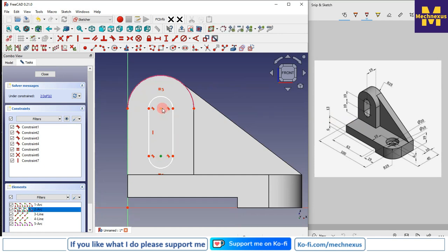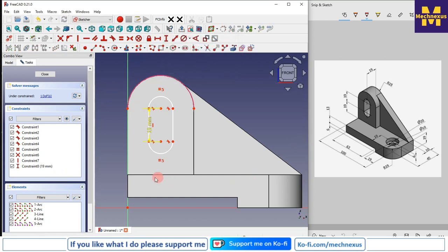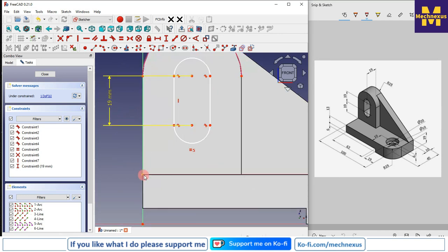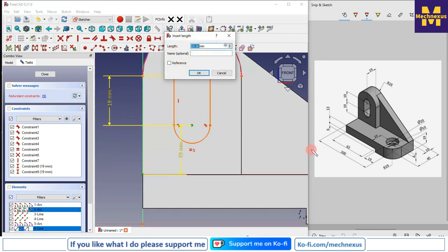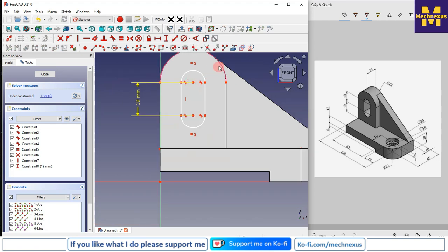So we will select this and give it 19 mm, and we will also click on project geometry, project it, and select this and give it 19 mm, which is already fully constrained because this center was already fully coincident with our projected arc.